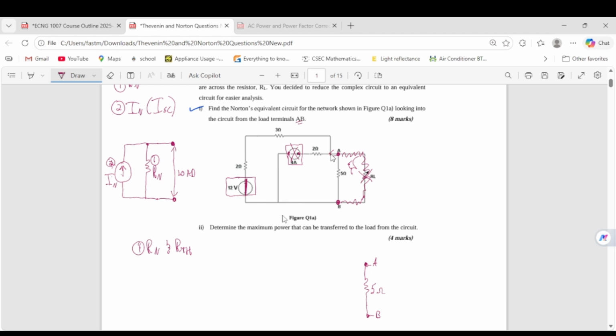And we keep going, we have this junction here. So if you look at it, this branch here has no current flowing because this piece is open circuited. This whole branch here is open circuited, because this piece here is no longer there. So there's a big break in the circuit, and if you have a break in the circuit, no current will flow. So you don't really have to draw this entire branch in the reduction.